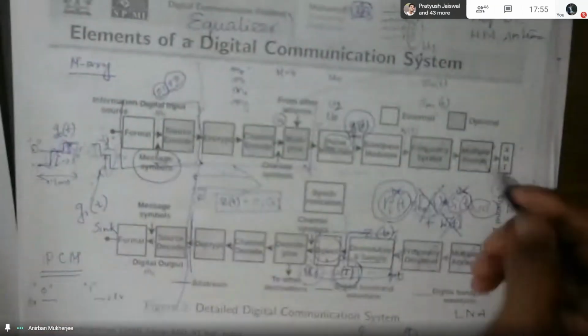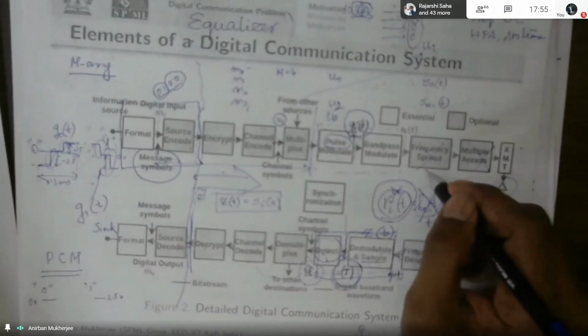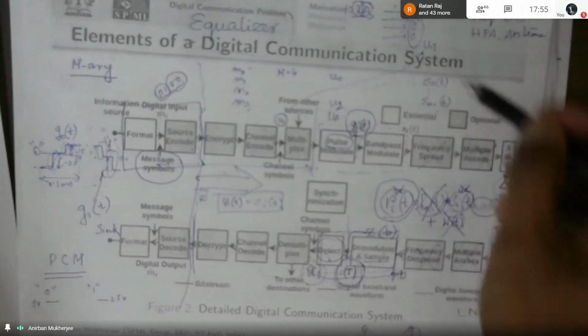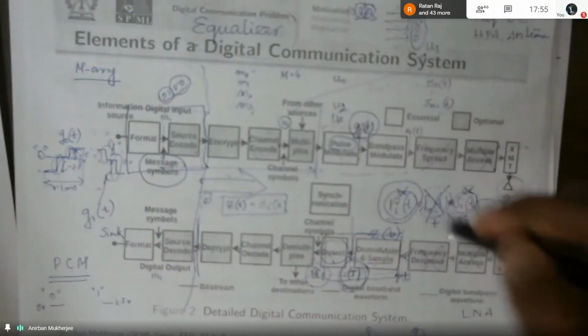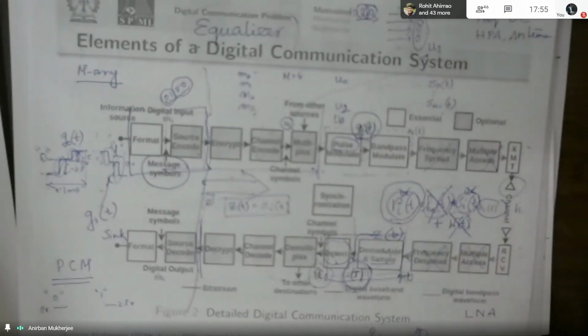And the frequency spreading that we discussed, basically frequency spreading can produce a signal that is relatively less vulnerable to interference, because interference can be from other sources, maybe unintentional interference, maybe your enemy likes to jam your signal. Okay. So frequency spreading means, say you are transmitting the signal in some particular band, say the 2.4 gigahertz band. Rather, sometimes I am transmitting at 2.41, sometimes at 2.39, sometimes at 2.42. And my receiver knows when I am sending what.